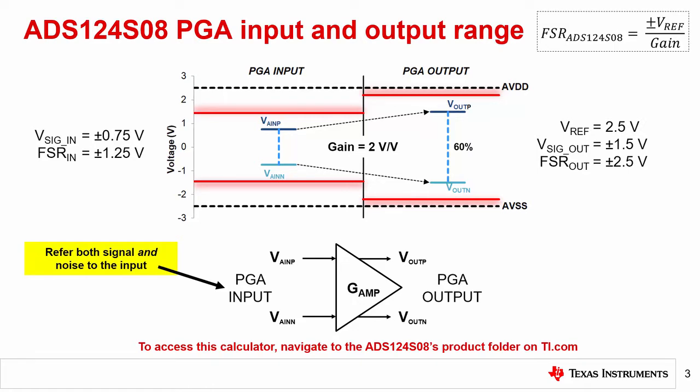And many systems do not require 100% utilization, so adjusting your settings or applying more gain might actually cause more problems than it solves. Second, ensure that when you calculate system performance specifications, you are using noise and input signal levels from the same measurement point in the circuit. As you can see, this module emphasizes that FSR is defined at the amplifier's input, not output. Many engineers mistakenly use datasheet noise parameters that are input referred while measuring a signal that is actually scaled by the gain.